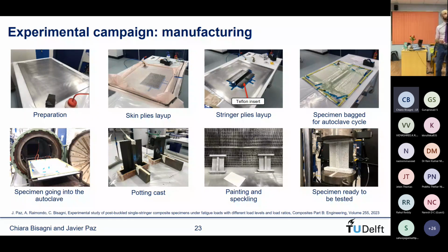This pink foil that we have is called the debulking foil, which is used to progressively compress the plies. So the rule of thumb is that for every ply you lay, you usually leave 3-5 minutes of full vacuum. Close the foil, apply vacuum through this nipple, and then once we're done, lift it up and lay a few plies again.